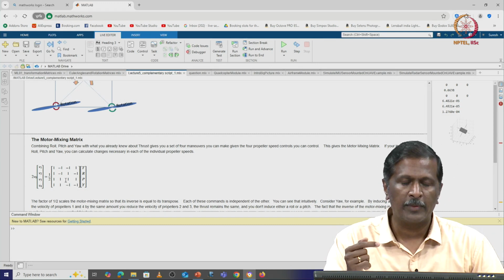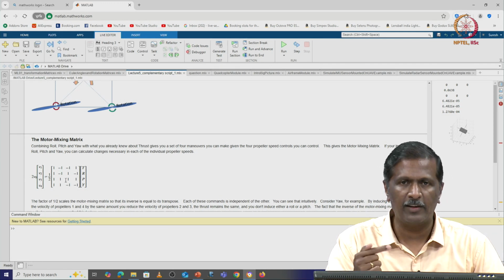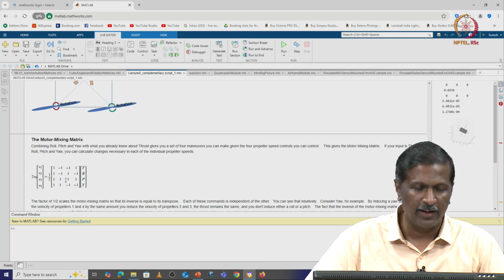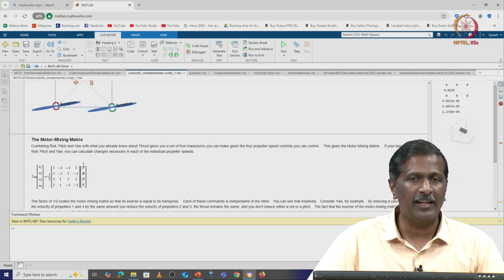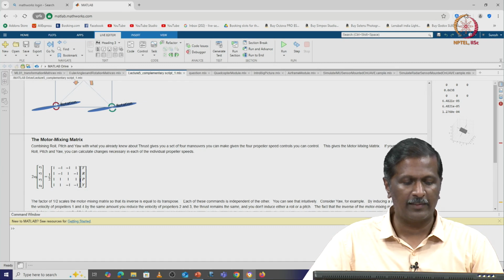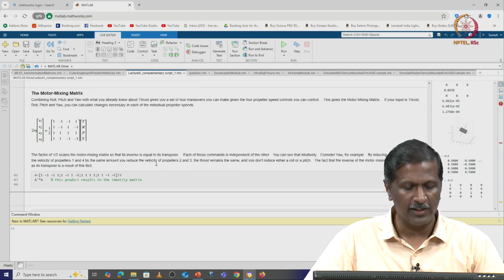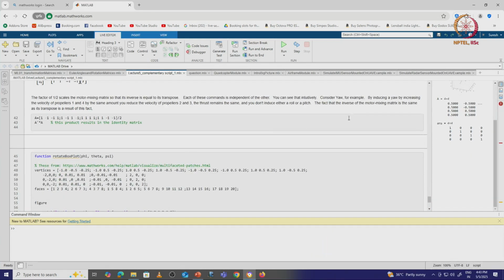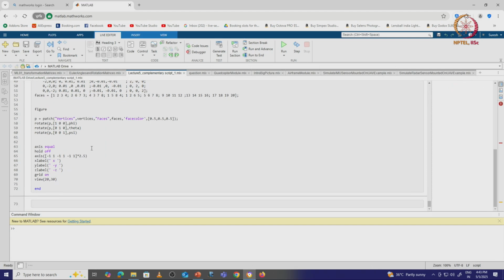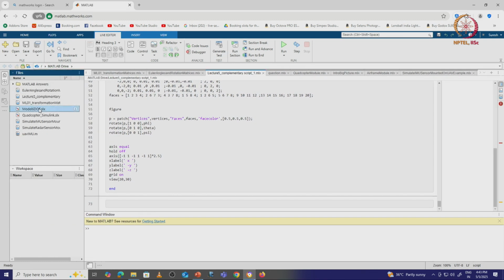The one difference from the equation of motion we did earlier is that there the thrust U4 was at the bottom. When we are implementing here, U4 is at the top. So, thrust, then you have roll, pitch and yaw. Okay. So, I get the necessary matrix, and I can add all these. So, I can get the function which is called rotate. You can rotate based on phi, theta, psi, and you can get your rotation accurately, right. So, once we do this, we can simulate the whole system of equations.